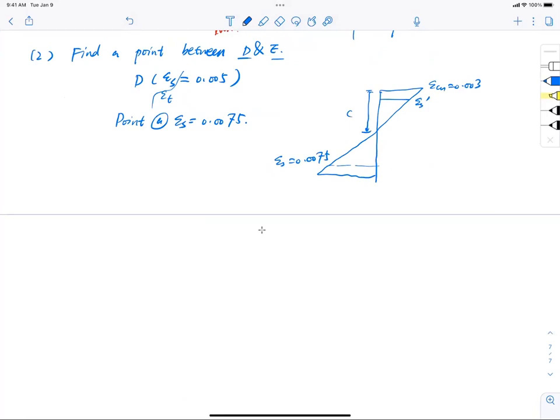All right, so start thinking about it. First thing coming into your mind: because it is in a tension control zone and is over the tension control limit, naturally the tensile stress in the bar has to equal the yield stress, because everything yielded.